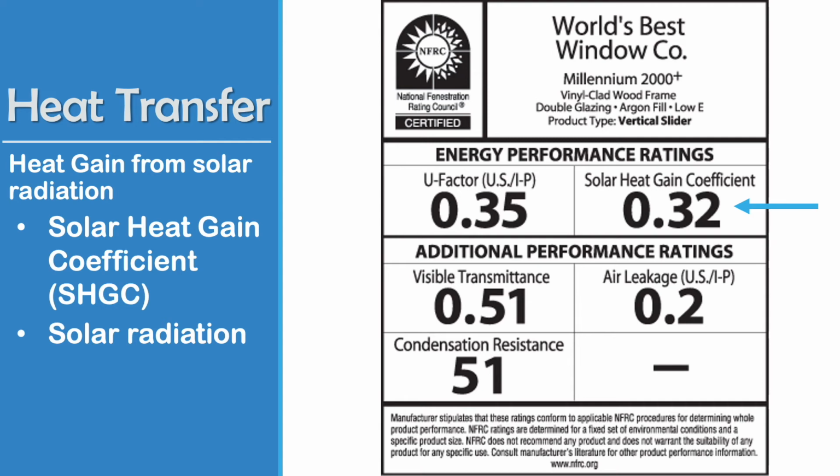So if views and high transmittance are important, also this comes into play with daylighting, we tend to want a higher visible transmittance, but it will affect some of the other items. So it's a little bit of a balancing act like so many other things are.